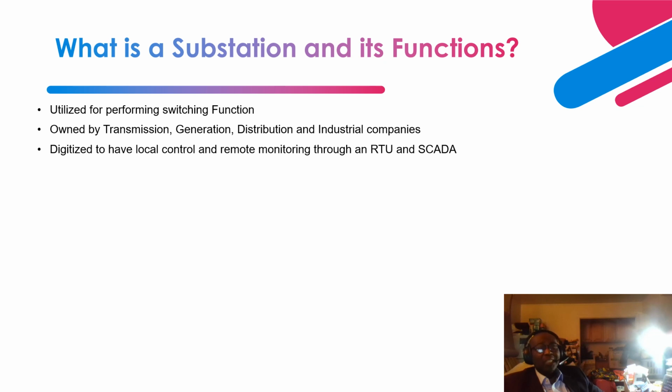The second switching function is after de-energizing the circuit breaker, right? We have disconnect switches. Those are no-load disconnect switches that have to be opened under no-load conditions to isolate the equipment so that the equipment can be worked on.